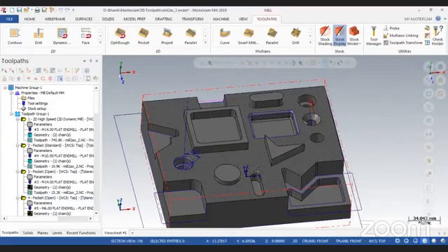So you just need to shorten it by adjusting many parameters. Tooling selection is the main thing. Tooling selection as well as feed and speed, cutter details, depth of cut, and many other parameters in calculation can affect the total cycle time.